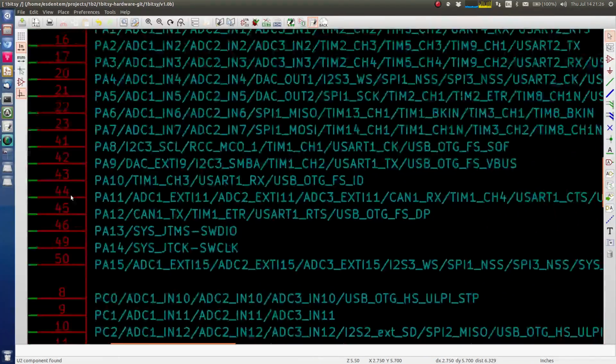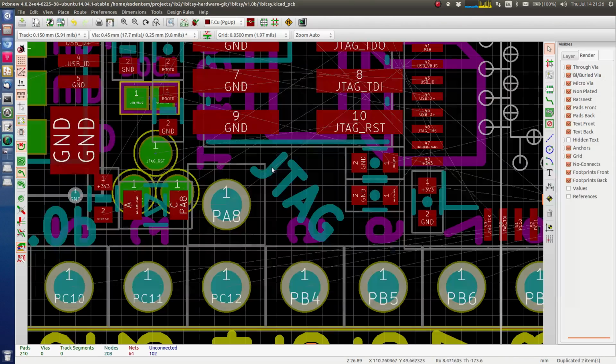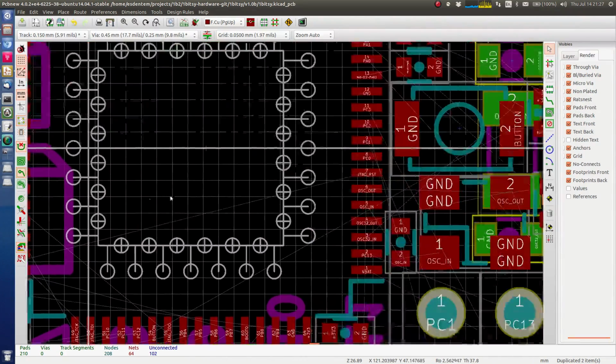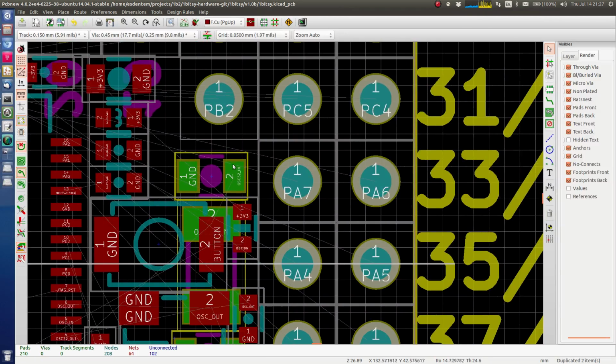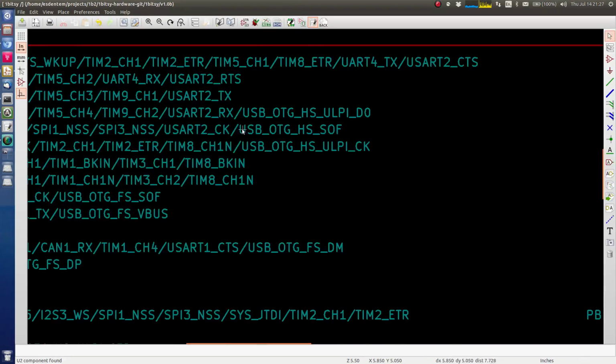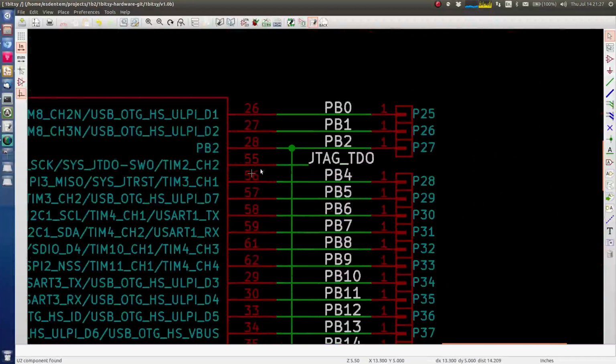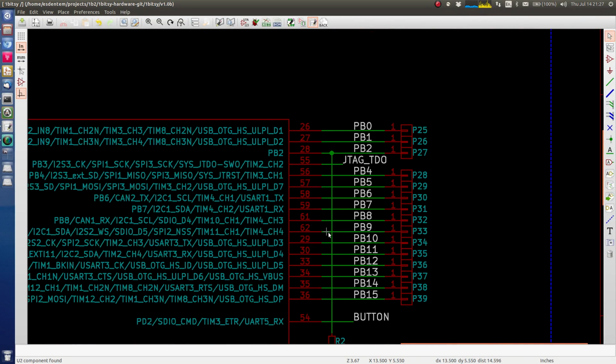This was the thought I had. Basically, the LED is connected to PA8, so that has PWM. I was thinking that I could move it over here and connect it to PB2 instead, and maybe even get rid of that pin. But the problem is PB2 is just bare. There is only GPIO on it. There is nothing else on this.